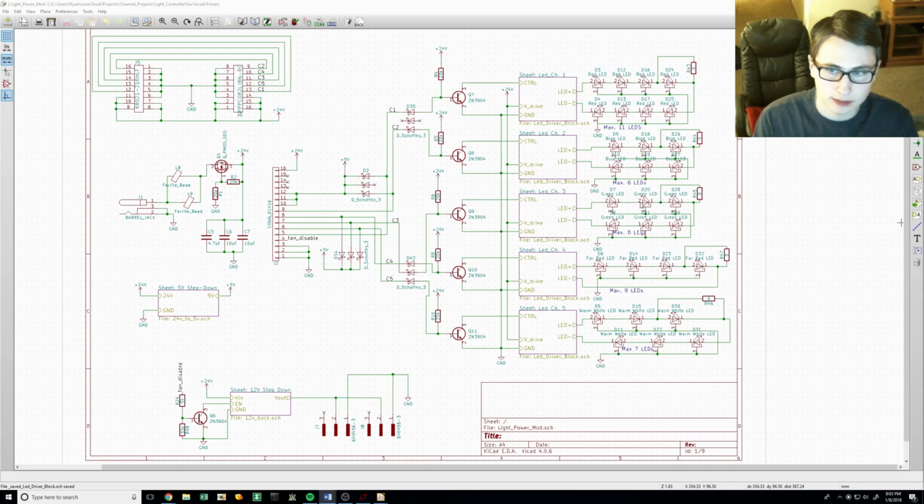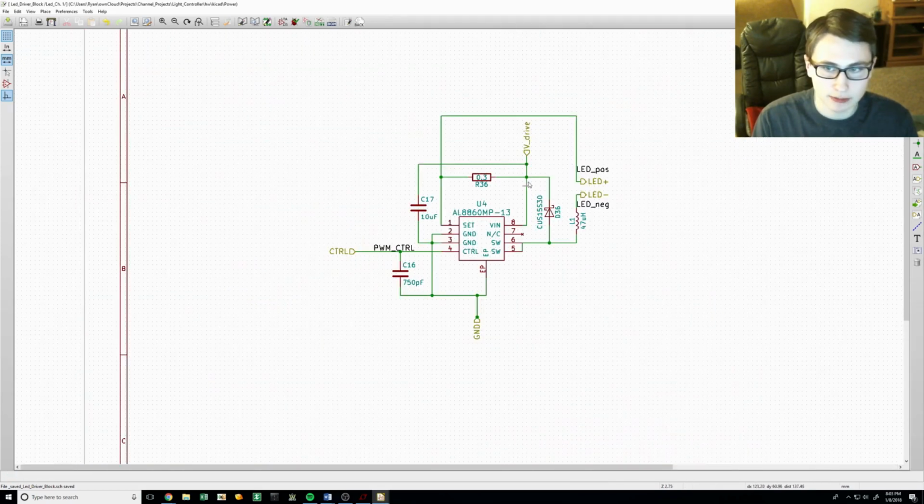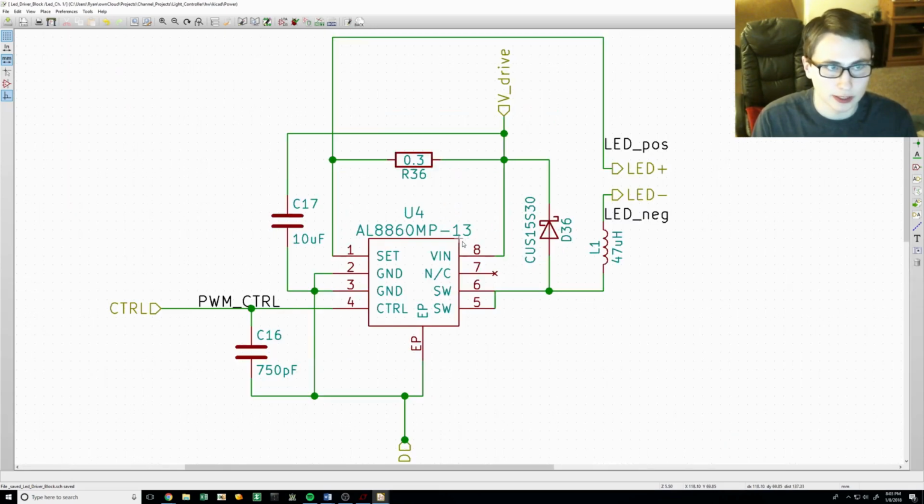Moving on to my design of the LED driver, let's open one of these switch mode power supply controllers. Now this is actually a clever use of a voltage regulator, tweaked slightly to achieve current regulation. This controller has an integrated low side switch and featured a reference design in the datasheet, which I leveraged when creating this schematic. I used the same rectifying diode as I used in the buck converters, since the diode I already selected met the current requirements of this circuit.